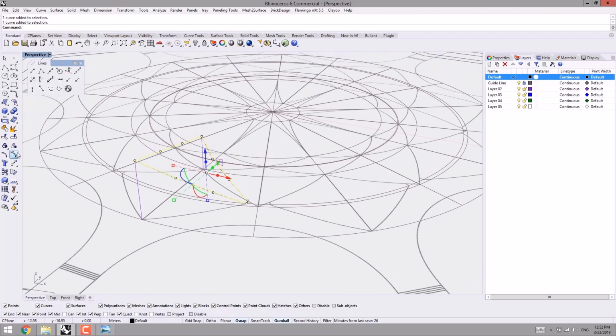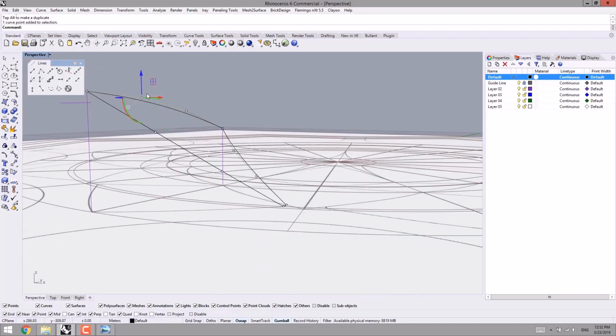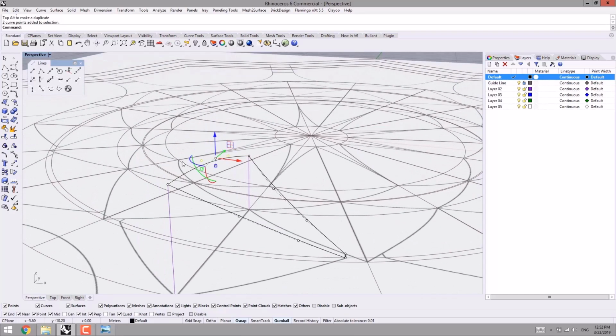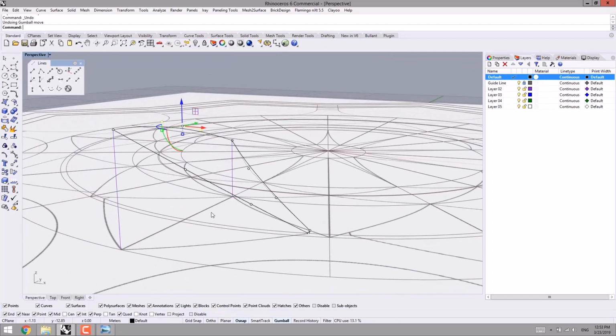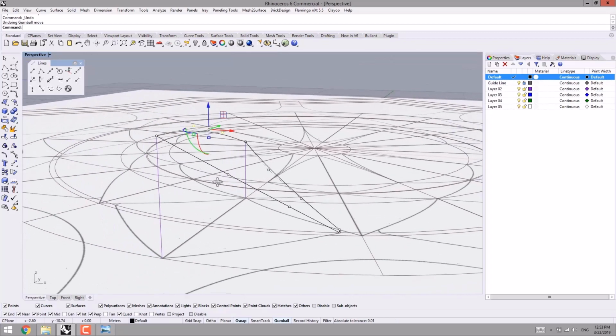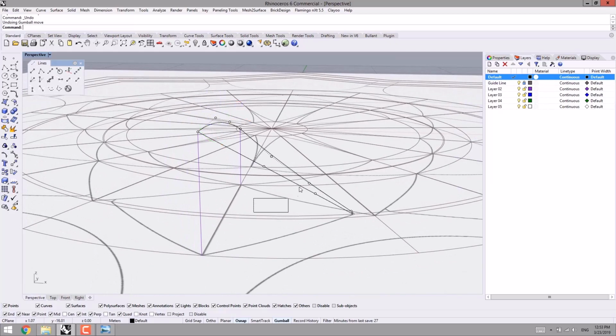Then I show the control points and then I adjust the curvedness by modifying them. But note that here we do not make any changes on the control points along the x and y axis, but we adjust the control points along the z-axis. Since if we make any changes or modify them, then we will have some problems in mirroring them. So we only modify the points along the z-axis.